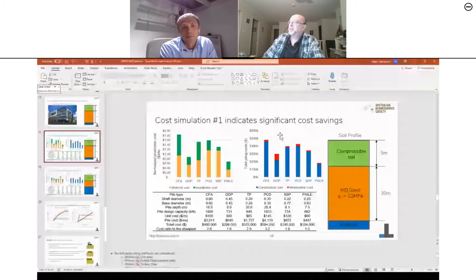Right. And can it be used in shallow water for offshore piling? Well, it would be, I guess, similar challenges as is the case with CFA piles. It's an open hole that is grouted. So once you get out of the ground and you have water above, you can probably grout it all the way up, but without seeing what you're doing, I'm not sure about that. That would probably require further research and more brainstorming sessions. Yeah, it does seem a bit pushed too far.